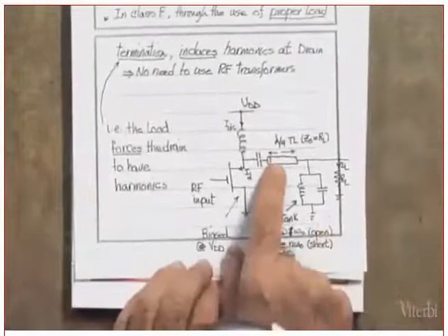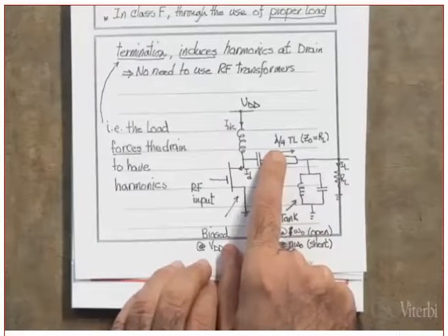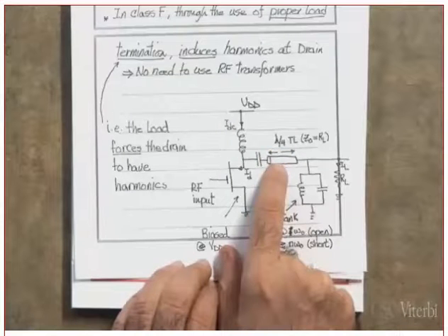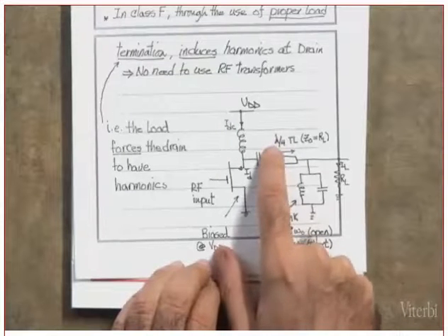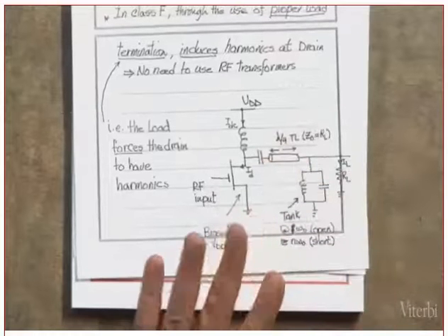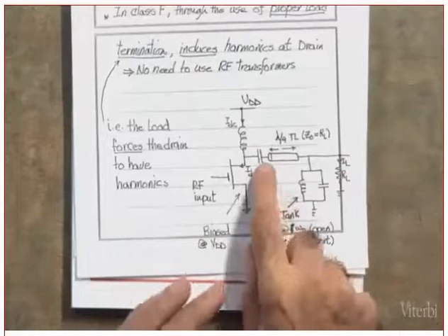So the length of the transmission line resembles a lambda over 4, a quarter of a wavelength of the fundamental frequency. This lambda is equal to c over f, where f is the fundamental frequency. And this is, of course, the blocking.